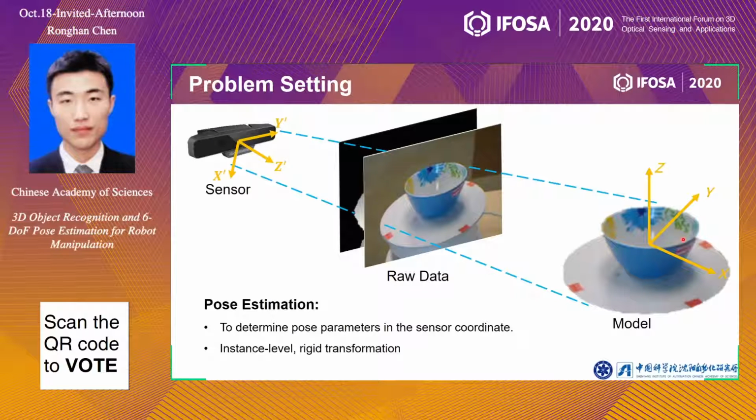As an example, I will introduce the most basic task in manipulation, the grasp task. Here's the pipeline of pose-guided grasp. First, the 3D model of an object is given, and the grasp labels can be obtained by manual annotation, simulation, or analytical methods. Then they can be stored to construct a grasp database offline.